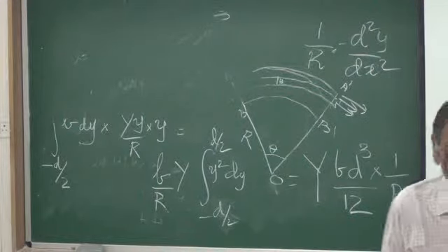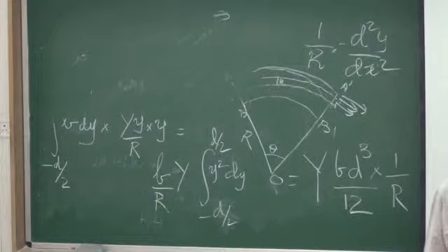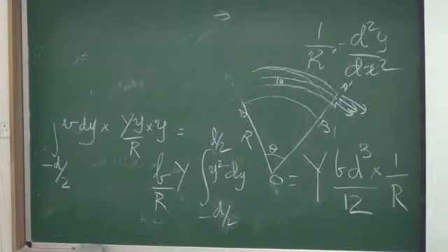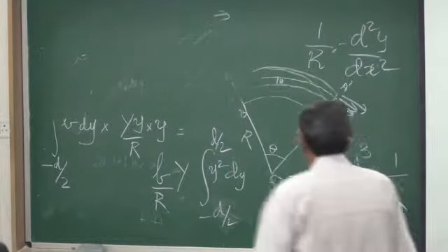You achieve uniform bending by putting the bar on two knife edges and putting a weight at the center. If you clamp the bar and apply a load, it is non-uniform bending. At different points along the length, the radius of curvature will be different.